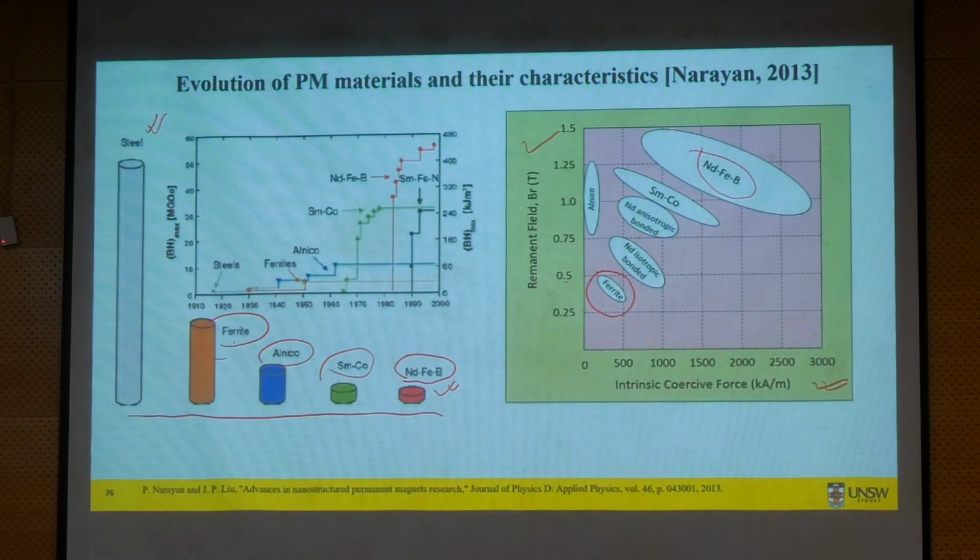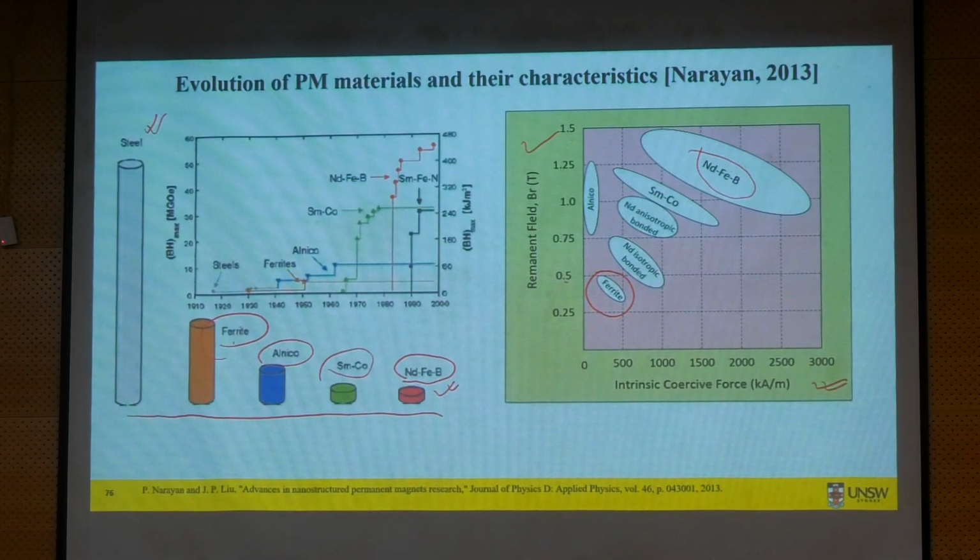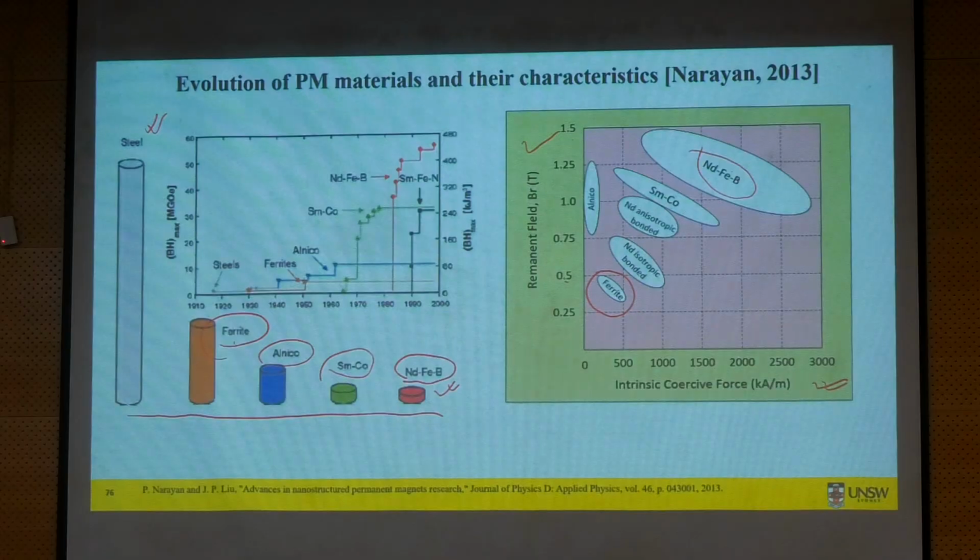Some of you, if you have ever dealt with a permanent magnet conventional DC motor, might have seen this kind of demagnetization happening, because those motors use ferrite. Sometimes DC motors stop working. Why will it stop working? Maybe you'll find that its magnets got demagnetized.